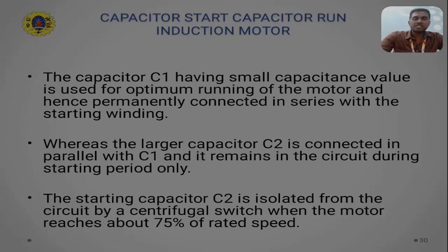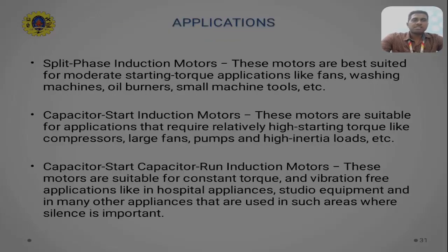In the previous case, both the starting winding as well as the capacitor get disconnected. Here only the capacitor C2 gets disconnected, whereas the starting winding along with the low value capacitor is in continuous connection with the motor.